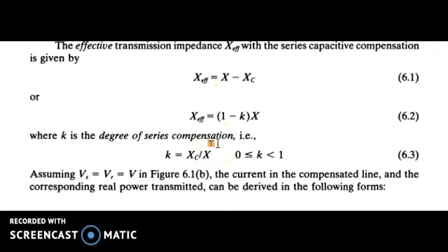Physically, that would mean what is known as the degree of series compensation, that is, to what extent our compensator compensates the effect of the transmission line. When we are having peak load periods, or heavy loads, we would need more compensation because the current through the inductance is more and the voltage drop through the inductance is more.